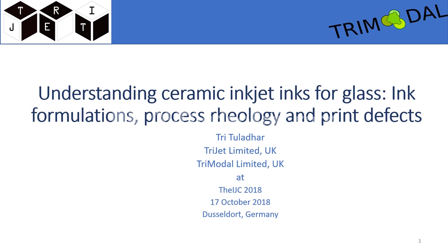What you think is Newtonian, what you think is laminar flow, doesn't hold true, right? The Reynolds number is still low, around 1, but I can make it a very, very chaotic flow in the printhead because of the microchannel device, right? The elastic turbulence becomes important. The elasticity, viscoelasticity becomes important. So what you think is a Newtonian ink when you measure it with a standard method is never Newtonian. For me, nothing is Newtonian. Even water is not Newtonian, right? It all depends on the time scale you're looking at it, right?